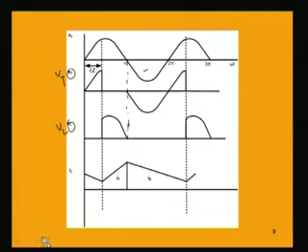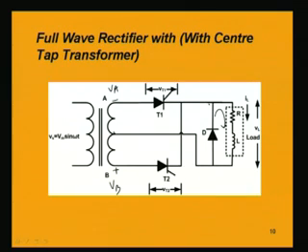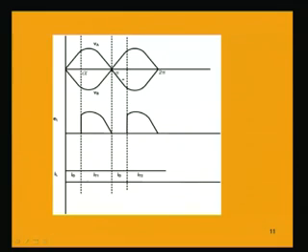So, in the full wave rectifier here we have seen that during the portion when the VA goes into negative half cycle before pi plus alpha angle, this is pi plus alpha, we have the voltage across this load 0, but the current which is flowing in the load is almost constant, because here the current which is flowing is the diode current,